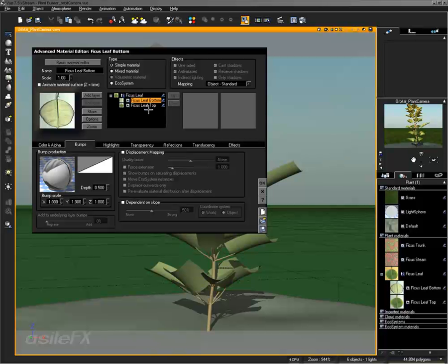16-bit grayscale PNG files are by far the best. Low file size, and you really can't turn the bump up this high without getting a lot of pixelation when you're close up, unless you have a 16-bit file. You might be able to get away with 32-bit if you're using EXR format, but it is more difficult to create the maps you need at that sort of bit depth.